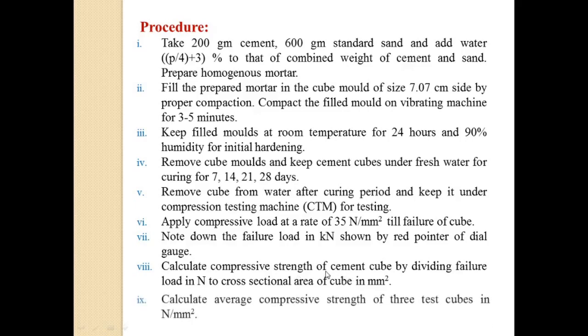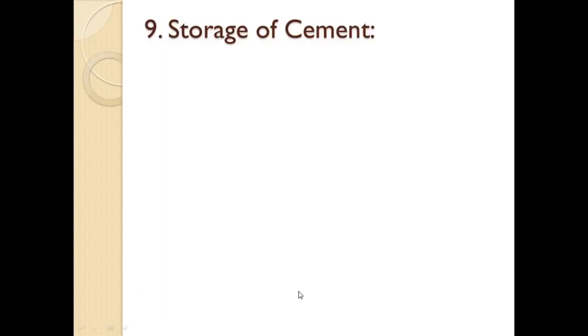Calculate the average compressive strength for 3 test cubes in Newton per mm square. So we have to calculate the strength for at least 3 cubes, so we can get the average for the test cubes. So next is the storage of cement.